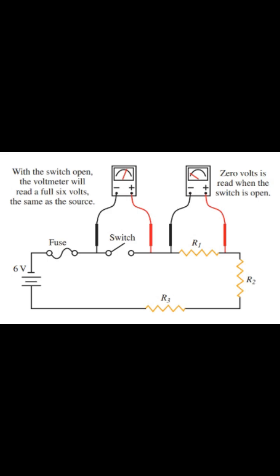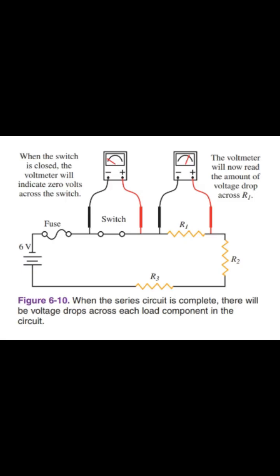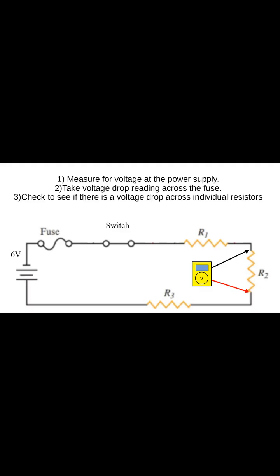The best instrument to troubleshoot a series circuit is a voltmeter. When referring to figure 5.4, if you put your meter across the switch, it will read however many volts the battery produces because it is open. If you push the switch down in the closed position, the voltage across it will decrease. With the switch closed, if you put your meter on each of the light bulbs, it will tell you the voltage drop of that particular bulb. If that bulb was open, the voltage drop across that bulb would read the battery voltage. In this type of circuit, there's only one path for current to flow, so no bulbs will light if you have an open in the circuit. See figure 5.4 again.